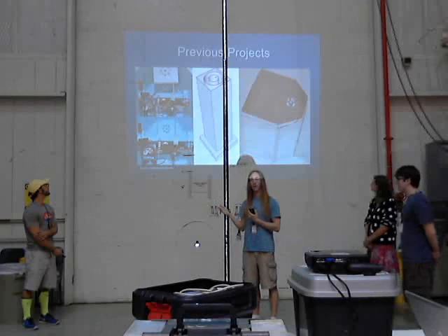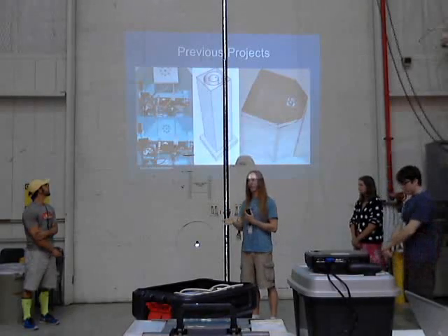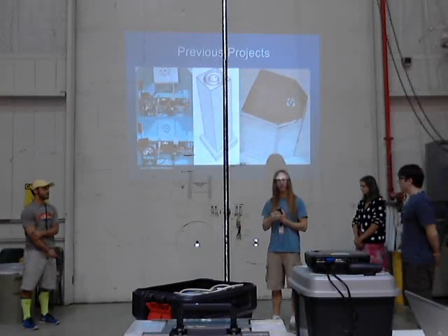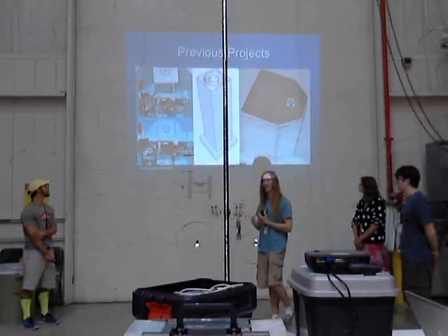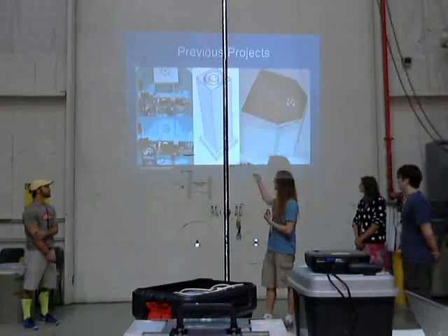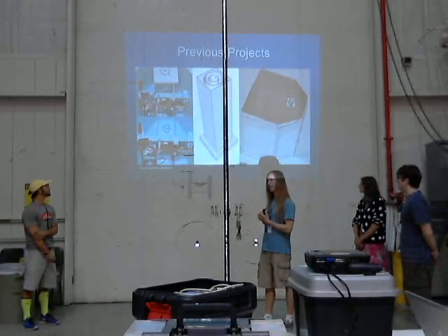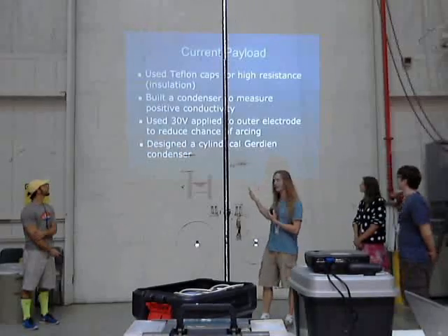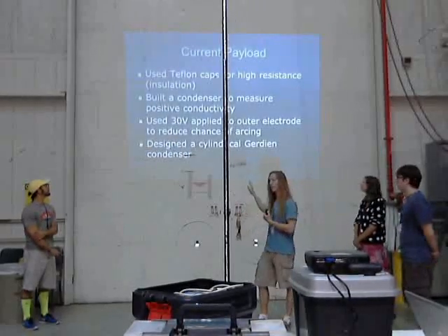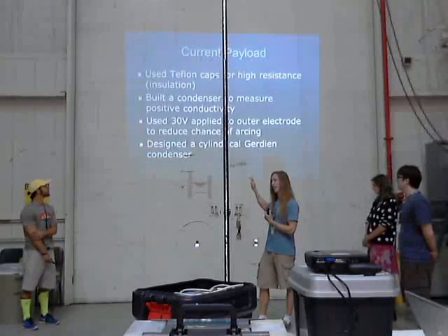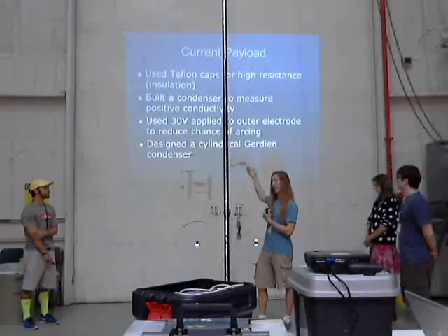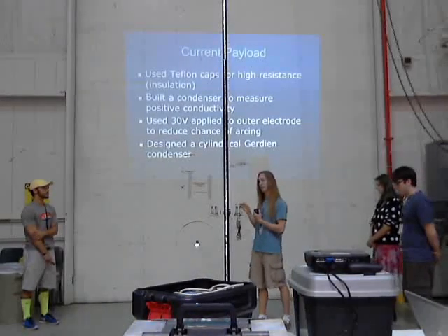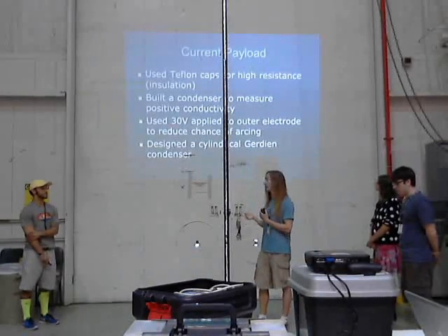We have been working off of some previous iterations that LSU has gone through, and we're very thankful to them for helping us along the way, fixing some problems we ran into. This is one of the previous payloads that went up, and this is what we're trying to improve upon. How we did that is they determined through previous iterations that the caps on the top and bottom should be Teflon. They used plastic, but even that was not insulative enough, and so Teflon is much better.